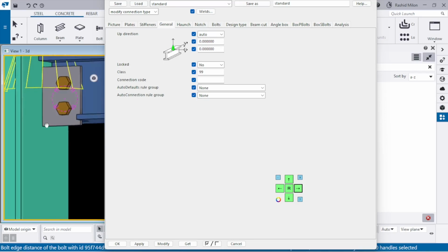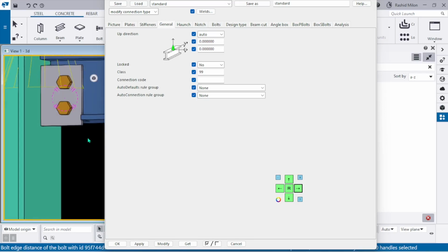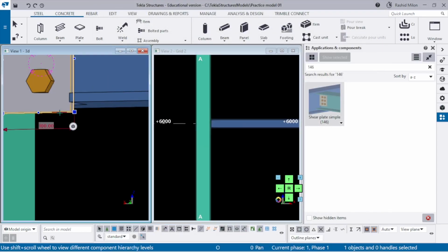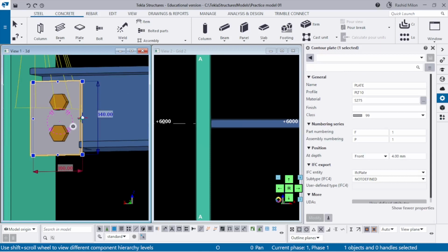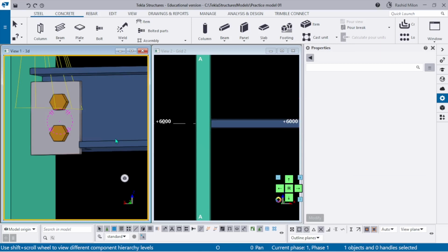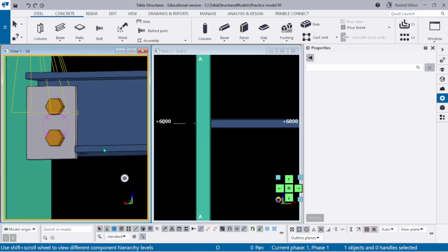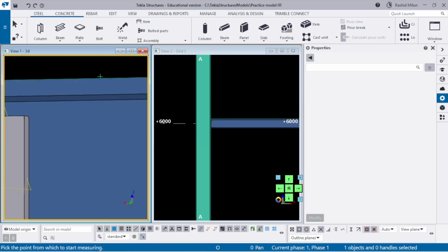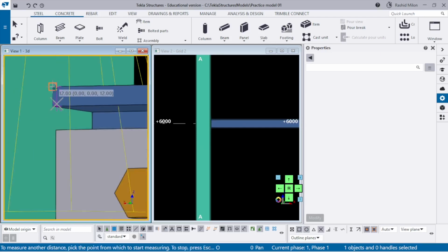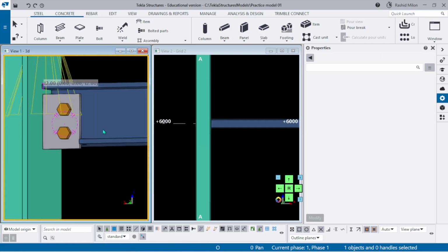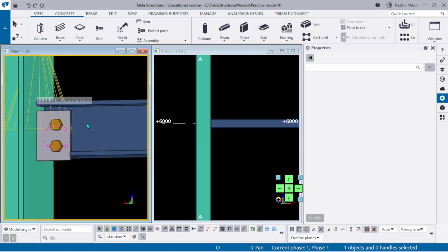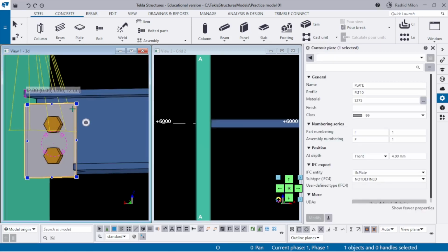All right, so now there is one issue here. The plate is a little bit bigger. So now we will make a smaller plate, no issues. The plate is 140 mm, the beam is now 150. Okay, so beam is 150, but from flange to flange we have to subtract the 12 thickness flange, so two sides is 24, so we can give 130 for our plate.